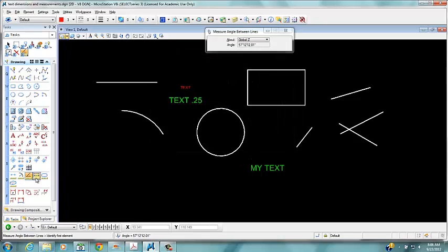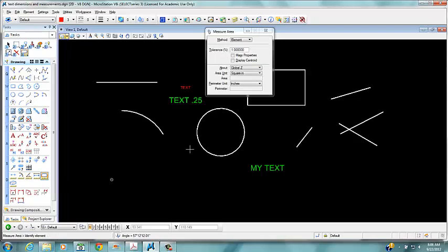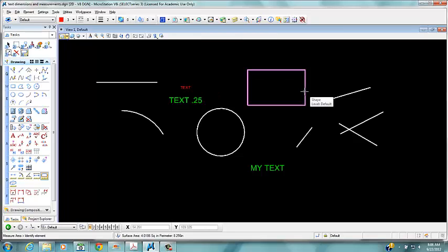So I want to measure the area. This is your area measuring tool here. If I want to find out what the area of the circle is, you just left click on the edge of it and it says it's 3.52 square inches, has a perimeter of 6.61. Here's this square shape, has 4.0186 square inches, and it's 8.256 inches on the perimeter. So it's a pretty easy and functional tool to use. It's set to element. We can also do it to an intersection, a union. It just has a lot of different ways to measure.